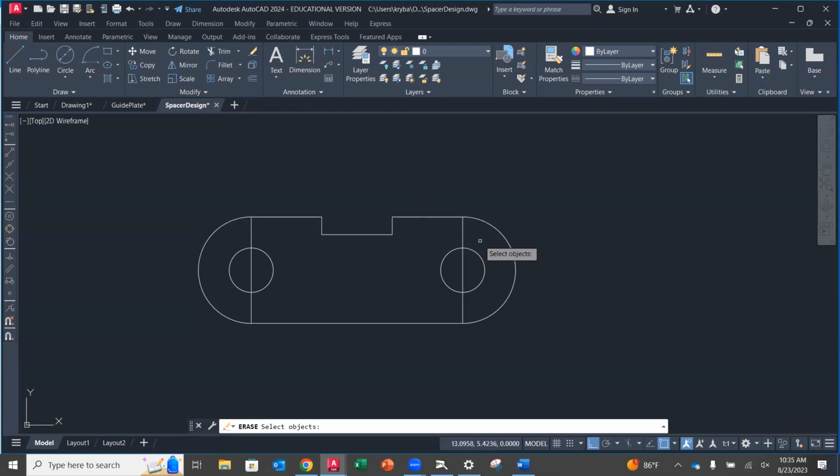And then I can do that selecting that you were talking about. I can start in the bottom left-hand corner and go over the top of it. If you do a click, click, it's a window. If you drag, it does that weird thing. Or you can individually select, or you can do the window from the upper left to lower right to get everything in there. Okay. So again, always tell AutoCAD what you want to do first.